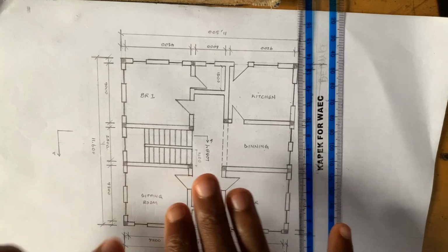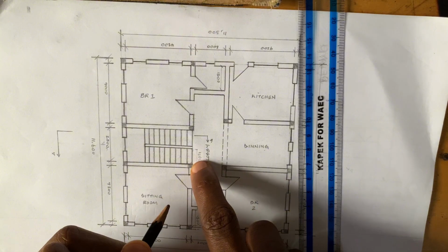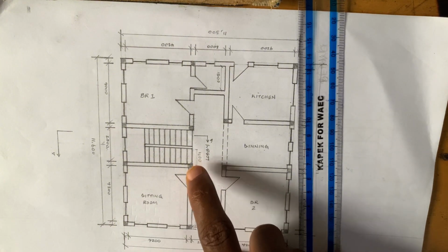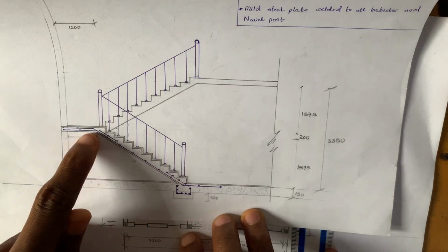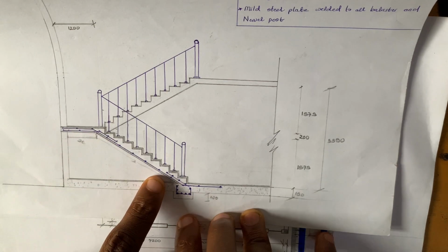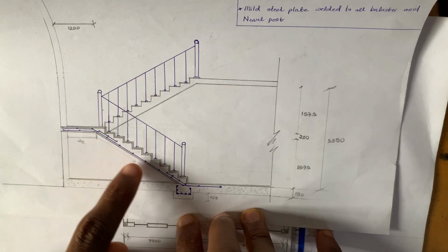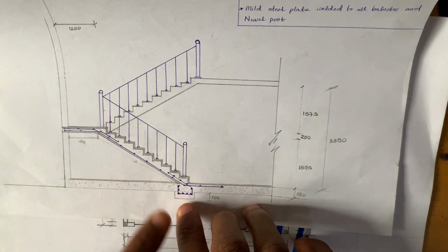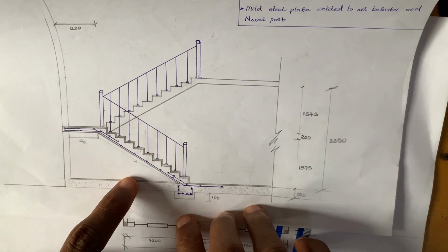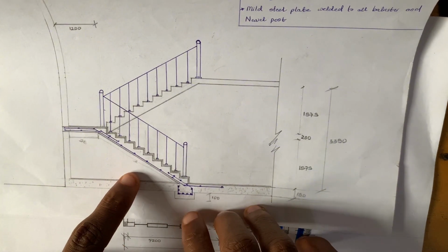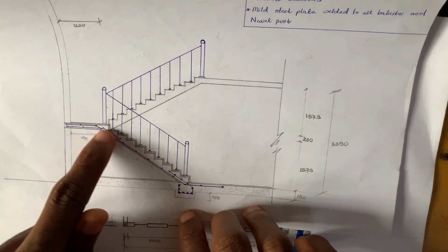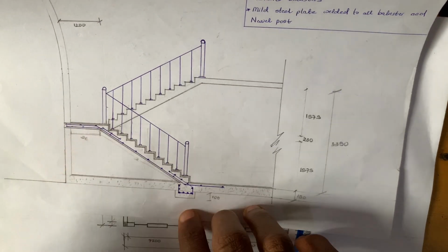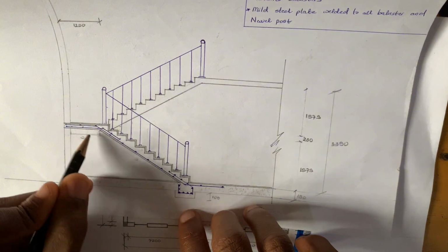So now that we've gotten our parameter y, like I said, the formwork to the surface of the string is measured in meter square. We've gotten the hypotenuse as x, and we've gotten the width of the staircase as y. So x times y will give me the area for the formwork to cover this part. So we've covered here, we've covered the landing.